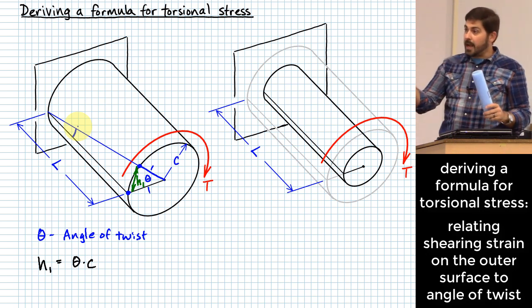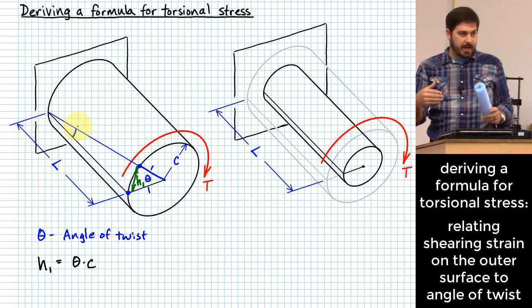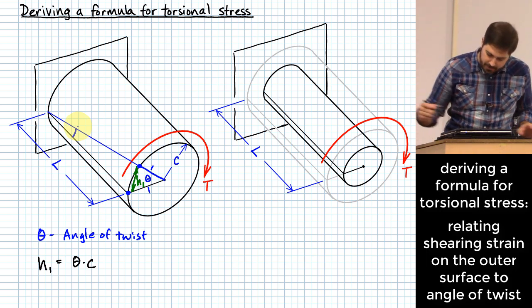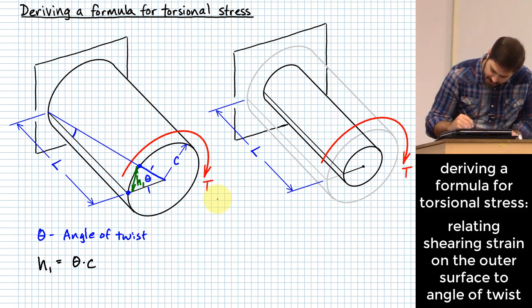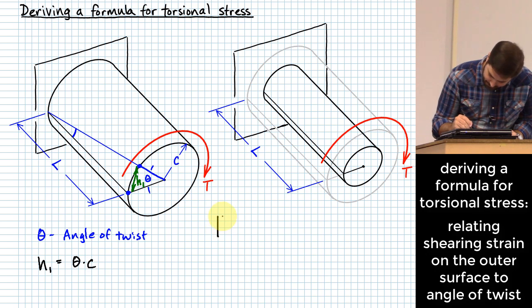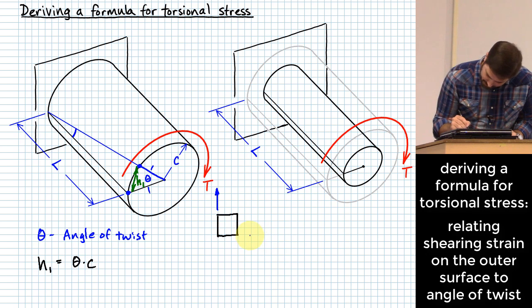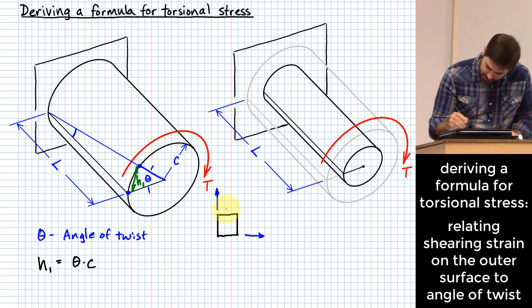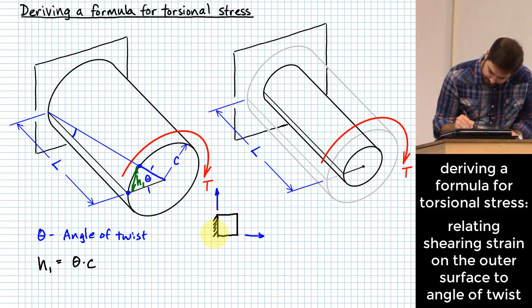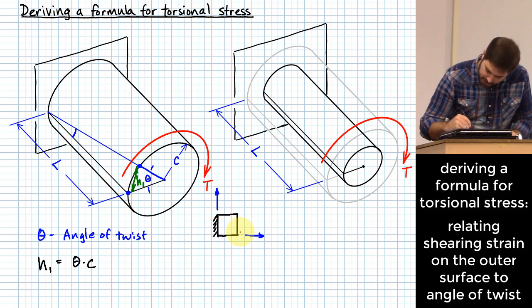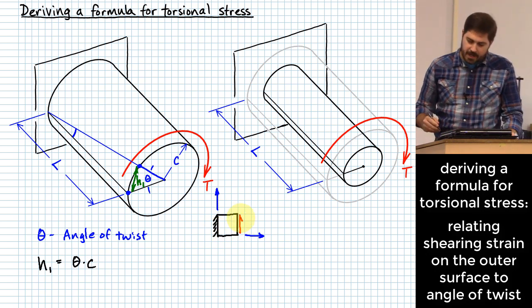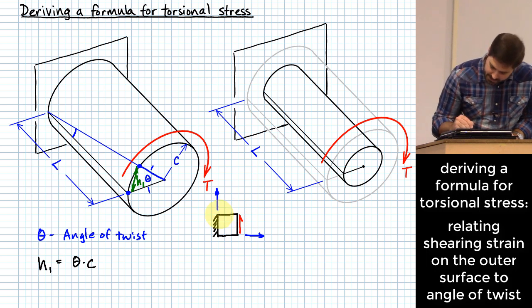Have we seen another stress element where that's what it did? Okay? Strain, and specifically shearing strain, you might remember, and I'll draw this a little bit funny probably here, but let's say that we start off with an element. I'll draw a little element like this. Okay? And if it's in a set of coordinates like this, and let's say I've got this end fixed, and then I put a shearing stress over here on this side, what we've seen already is that this member is going to become kind of parallelogram in shape,